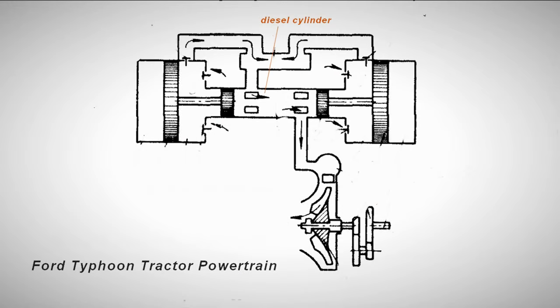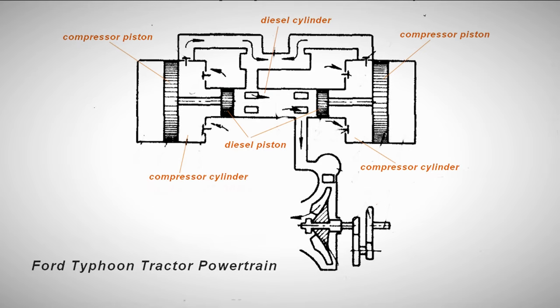The diesel cylinder diameter was 3.75 inches, and the compressor cylinder diameter was 11 inches. The piston stroke varied from 4.2 inches to 6.8 inches at different operating conditions. The compression ratio in the diesel cylinder at the calculated power was approximately 30:1. The gas pressure at the generator outlet was about 3.62 bar.